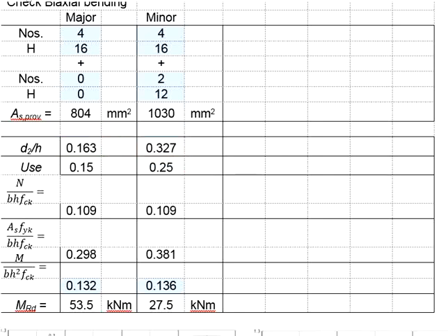On that basis, we shall refer to the chart with the D2 per H ratio closer to it. Let's say in this case, we choose to use the chart 0.15 and 0.25 for the major and the minor axis respectively.